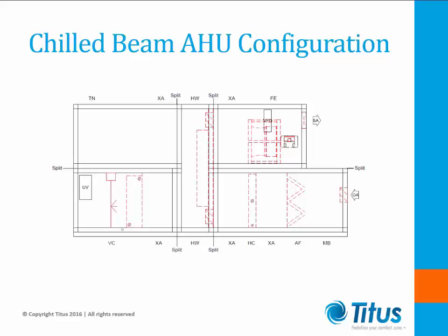Other methods of decreasing air handling unit energy is by use of heat wheels. A two-pass heat wheel will pre-cool the incoming airstream prior to the coil, allowing the cooling coil to expend more energy on the latent cooling side. After the air is cooled and dehumidified by the cooling coil, it will make a second pass through the heat wheel. The air will now be cold and close to saturation and will now pass moisture to the wheel while cooling it and thus dehumidifying the supply airstream further.